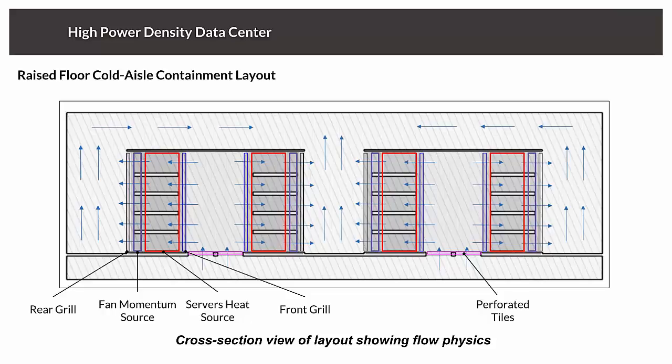So the server heaters will be represented by a certain virtual volume that introduces heat into the air. To allow motion of this air, we'll use another advanced modeling technique, that is, we'll introduce virtual momentum sources that will mimic the presence of the fans that will be taking the air away and out from the servers themselves.